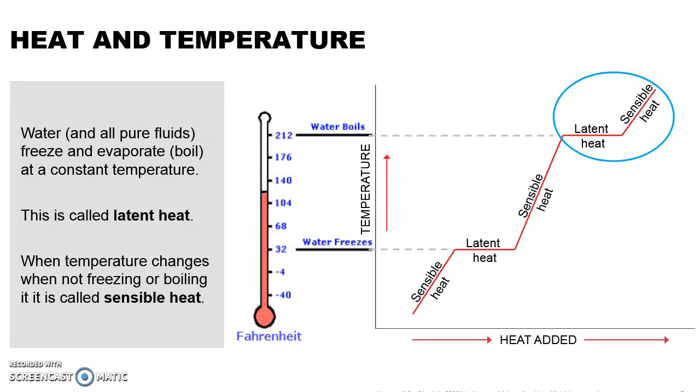For instance, if your home air conditioner is using the refrigerant R22, the evaporator will have liquid R22 boiling in the evaporator at about 45 degrees Fahrenheit. Of course, the pressure is not going to be atmospheric, 0 psig, like in this water example. But the R22 is doing the same thing as the water boiling at 212 degrees. It is boiling at a constant pressure and temperature. It's just that R22 has different characteristics and boils at a different temperature.